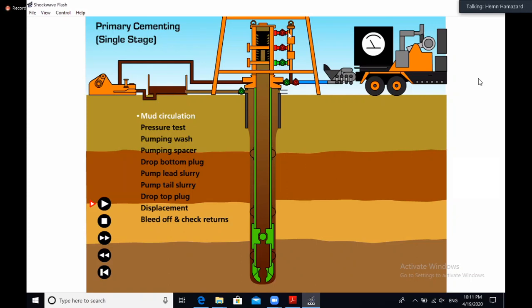Here there are a lot of valves and connections, typically about 40 meters of pipe connection, and there's possibility for leaks. So you close this valve or any valve somewhere else, so you can apply pressure from this cement unit using just water. You inject water into your pipe until you see a pressure and wait for a certain number of minutes. Then you make sure your lines are holding pressure before you have any failure downhole.